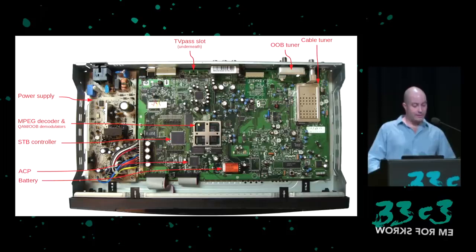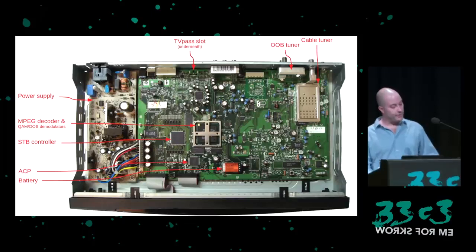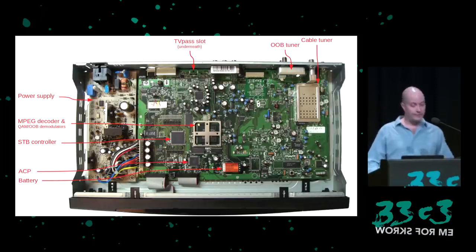A TV pass slot is underneath the main board. It's not visible in this photo. The cable set-top boxes include a second tuner that's used to receive the out-of-band data. This out-of-band tuner operates independently of the main tuner and on a separate frequency range, and it's used to provide a transport stream containing the system information with the program guide, firmware updates, EMMs, etc.